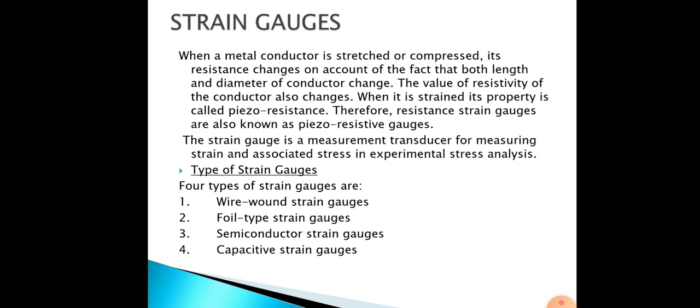The next one is the strain gauge. In this strain gauge, when the metal conductor is either stretched or compressed, its resistance will change, on account of the fact that both the length and diameter change, so the resistivity of the conductor also changes.